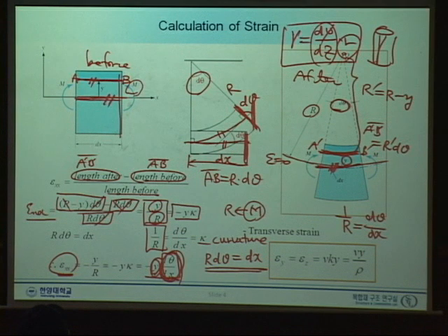And back to here, you can always calculate the strain as well. But in most cases, the stress is more important. Once you have a stress, you can always calculate the strain. But remember that this strain distribution has nothing to do with the material properties. It's very much similar to a torsion case. In torsion case, always the gamma is linearly varying from inner to outside.